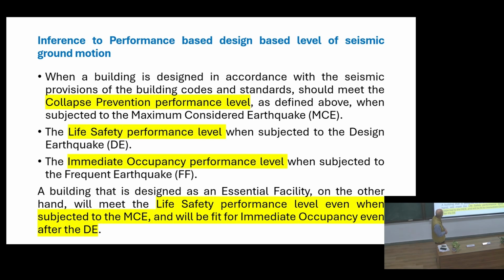So next one is that. Those are the performance levels; we talk about 4 levels, and they have been elaborated like this. So immediate occupancy performance; I mentioned various levels of occupancy. This is when the structure is subjected to frequent, regular earthquakes. We do not expect a big one here, but small earthquakes always come, like in Jaipur, where you feel it. Sometimes you don't feel it also. So for frequent earthquakes, that is how you classify the immediate performance level.